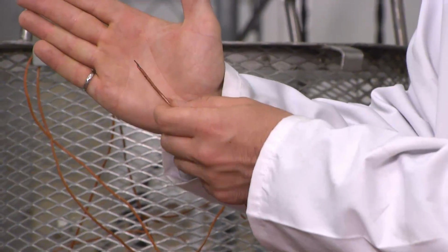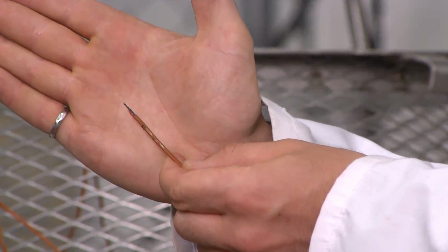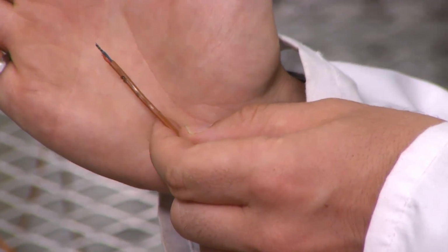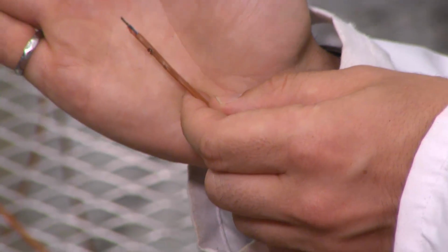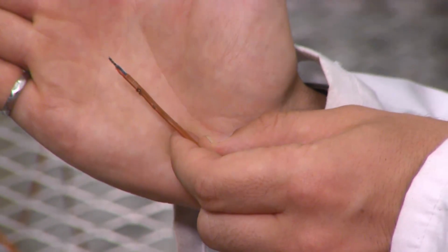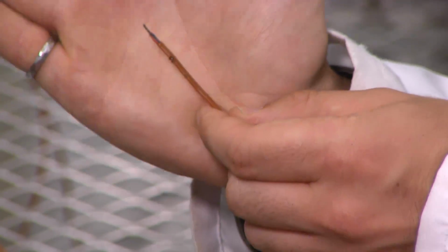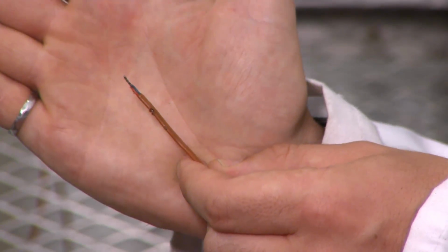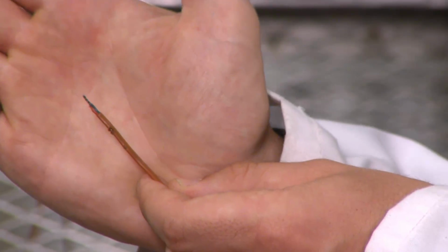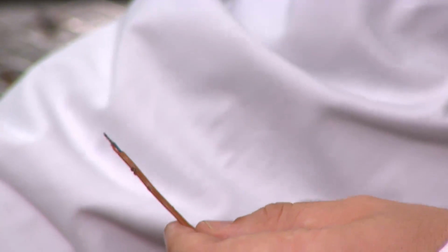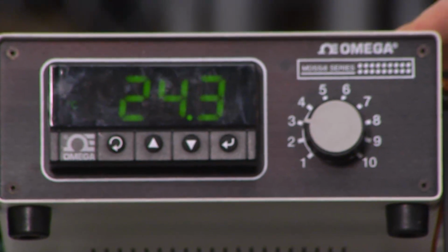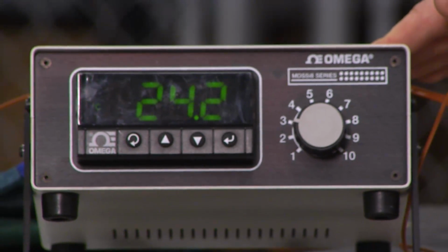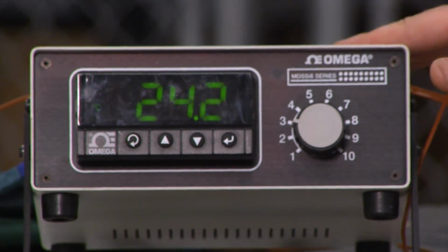Now, if you can take a look at one of the thermocouples, we've chosen T-type thermocouples as the temperature range will be adequate for this experiment. This thermocouple, as you can see, is very inexpensive. It is simply the two pieces of copper and Constantan wire welded together and connected currently to a thermocouple reader. It is currently reading the ambient temperature of the air around us. It's a little warm. We're filming in the summer, so it's reading at about 24 degrees.